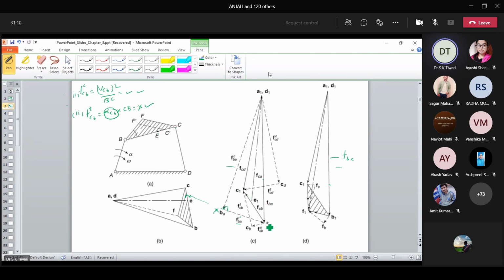This is my point B. Okay? Yes, sir. And CB is the center of rotation. I'm going to plot this component FCCB. The magnitude coming from the vector diagram looks very small. B is the center of rotation. Since it's the centripetal component, it will move away from B in this direction, parallel to the arm CB.